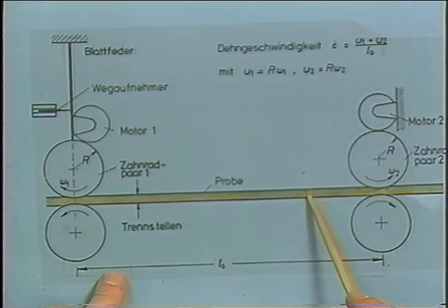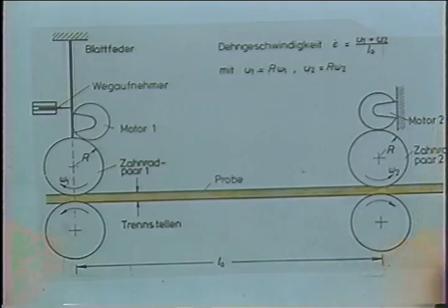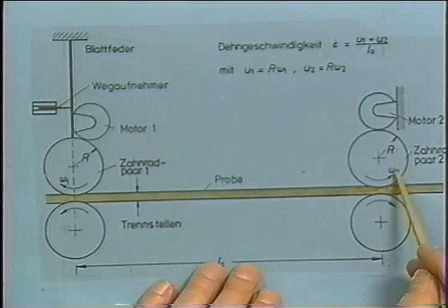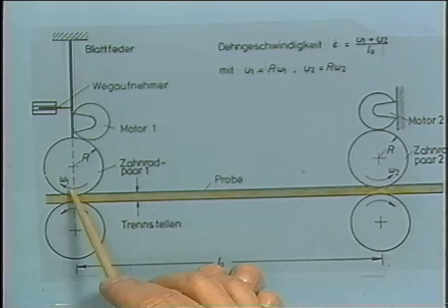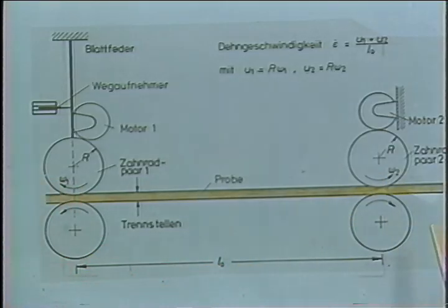The diameter of this sample is decreasing, is shrinking as the stretching goes on, as the fiber gets smaller and smaller. So the rolls have to accommodate that. They have to move closer together during this grabbing. The kinematics of constant extension rate is achieved by choosing a constant speed of rotation for these rollers and those rollers. The speeds don't have to be equal. Normally this speed is very slow and this is high, but just make sure that new material is being grabbed all the time.